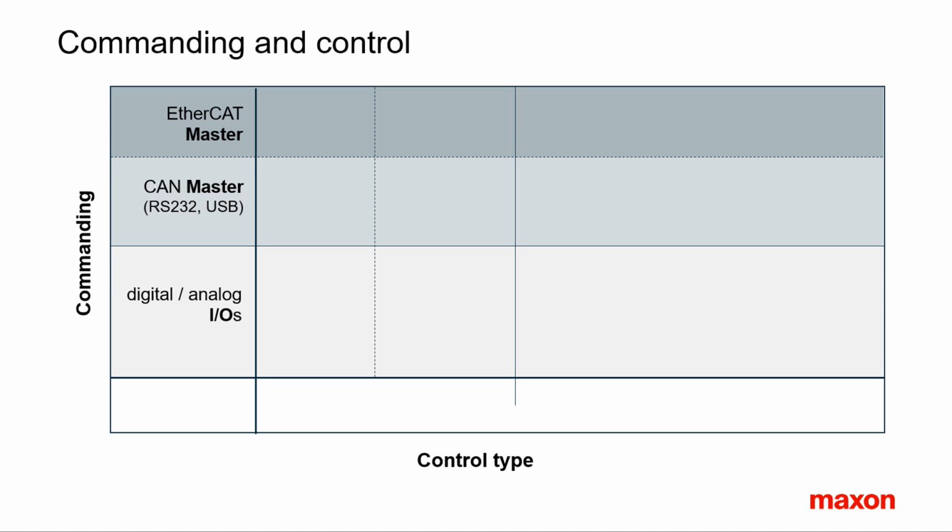The second feature is the kind of control. There are three main types: torque control, speed control and position control. Torque control on motors is equivalent to current control. It's the lowest control level. Controllers with a torque control mode may be used as inner loop in an external speed or position control loop. In speed control we have to distinguish between simple one-quadrant speed control, usually working with low resolution feedback, and dynamic four-quadrant speed control with higher resolution feedback.